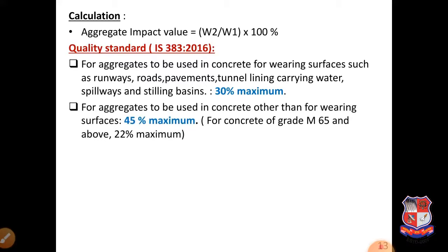For aggregates to be used in concrete other than for wearing surfaces, it is maximum 45%. Also, they highlight that for concrete of grade M65 and above, the maximum aggregate impact value is 22%.